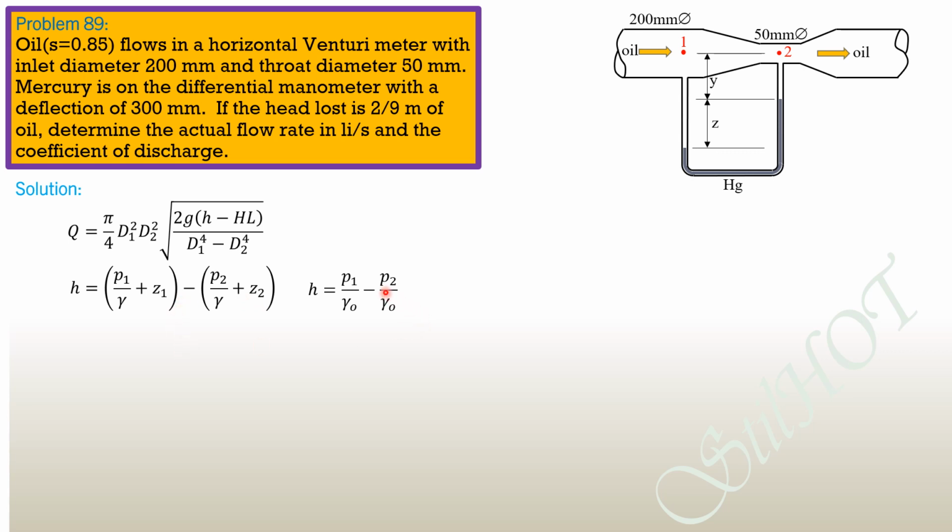So we then sum up pressure from point 1 to point 2 along this tube. So P1 plus the specific weight of oil, the flowing fluid, times the quantity y plus z. That's the present or current pressure here. So the pressure here is equal to the pressure here by the principle of the same level in a homogeneous fluid at rest. Then we rise, so minus the specific weight of mercury, the manometric liquid, times z, then minus gamma, the specific weight of oil, times y equals P2.